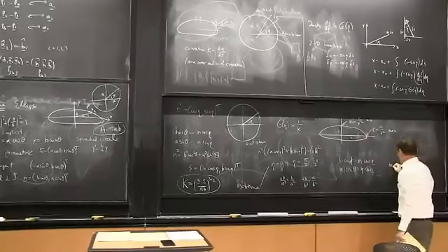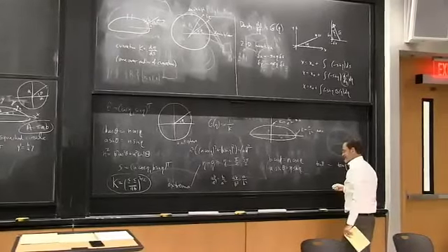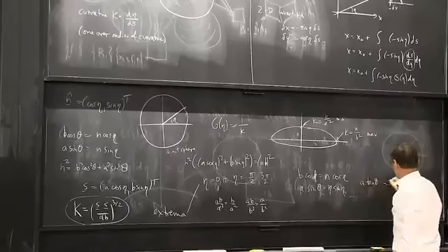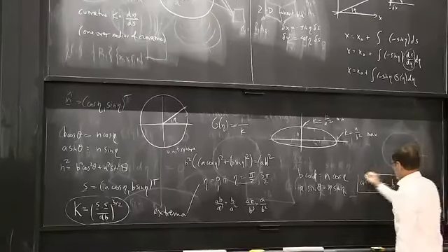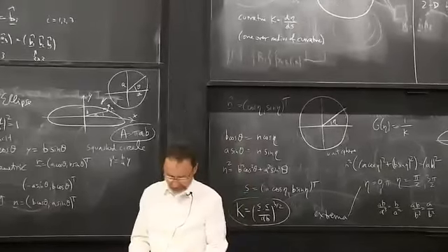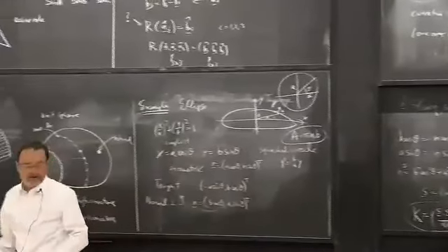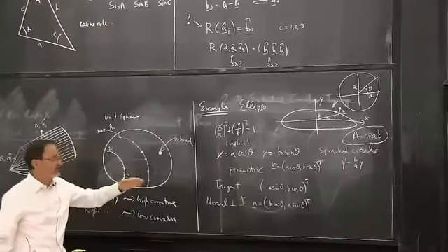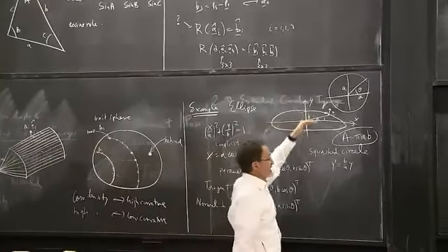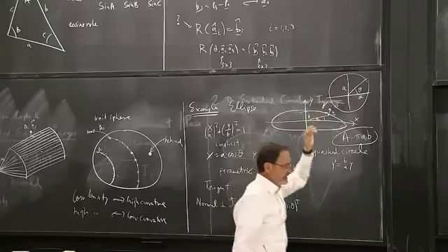So tan theta is related to tan eta by something like this. And if I got it right, this is an important formula used in geodetics because it relates the geocentric angle, the angle we make at the center of the Earth, to the angle of the latitude that we use for computing latitude.